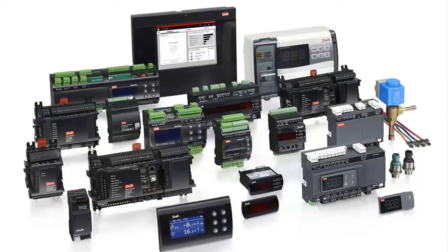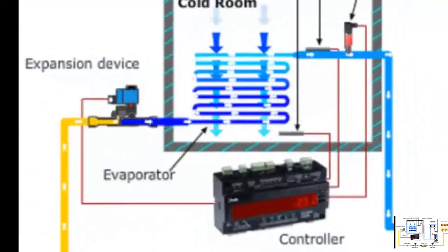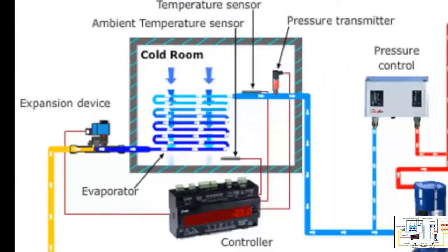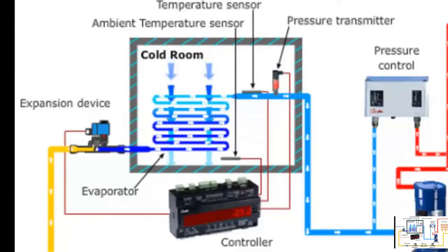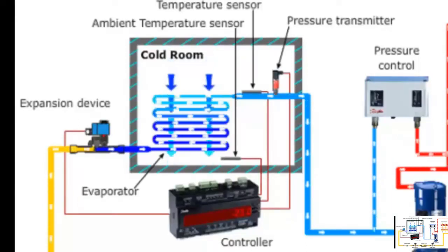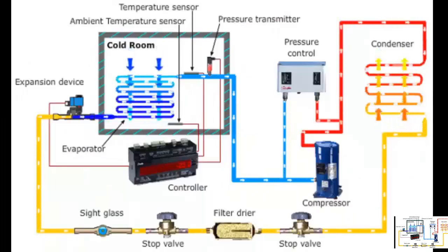12. Cold room electronic controller, responsible for managing the electronic expansion valve according to the pressure and temperature values provided by the sensors. This precise control allows accurate control of superheating at the evaporator outlet, saving energy, and protecting the compressor. It also allows handling variables such as temperature, air velocity, humidity, among others.